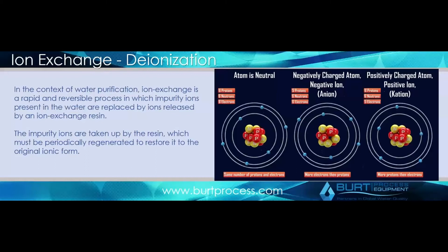When you're talking about ion exchange, either chemically or as an EDI process, we're going to talk about chemically here first. You're essentially exchanging a charged ion for another charged ion. So as you pass water through, you're swapping either a cation or an anion for a proton or a hydroxyl to basically form water.